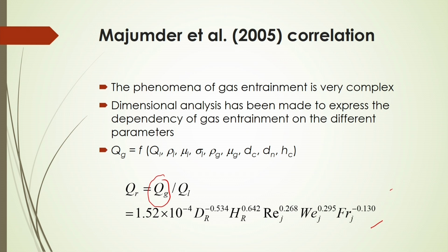This is very important because if you have a higher jet velocity, your Reynolds number will be very high, so turbulent conditions will be created, and the bigger bubbles formed in the plunging region or intense mixing zone will break up. So you can get finer bubbles at high Reynolds number of the jet.